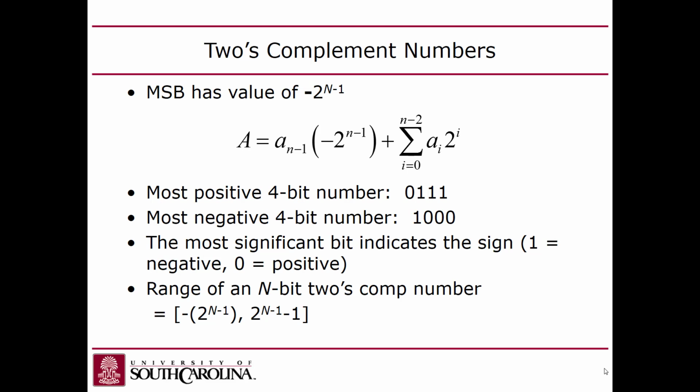If you add two negative numbers, you shouldn't be getting a positive number, right, or 0, right? It's impossible, right? So in that case, yeah, we still got a carry. So again, that one you'd have to look at the sign bits.